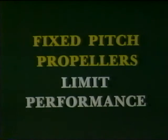A fixed pitch propeller must be chosen to give the desired performance for only one set of circumstances. For example, a propeller designed to give optimum performance at cruise will result in an abnormally long takeoff run and slow climb, while a propeller that performs well at takeoff will result in a slow cruise speed.